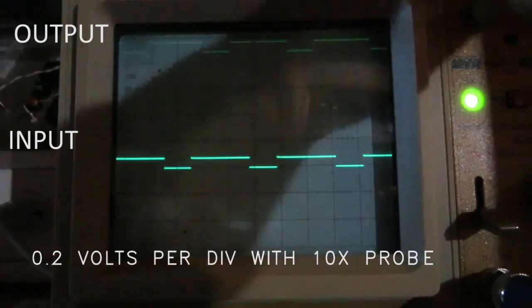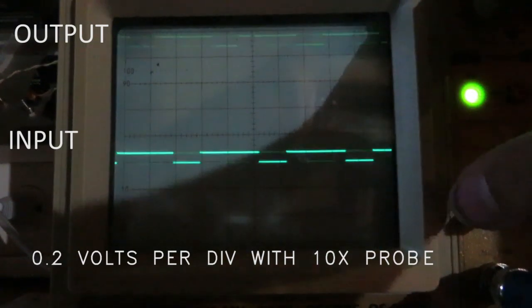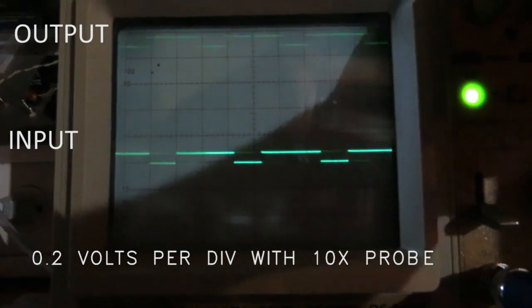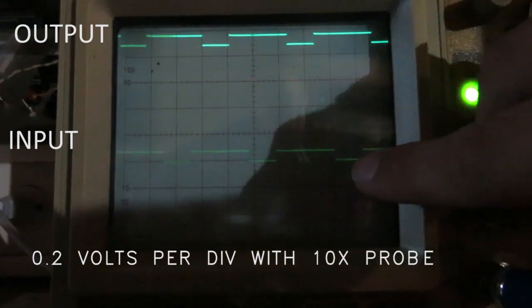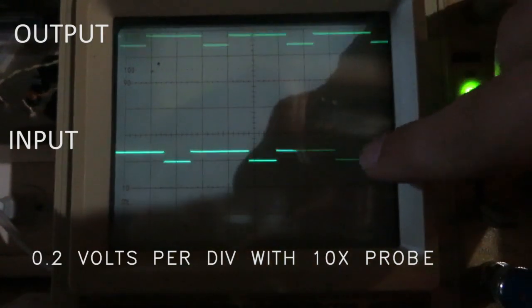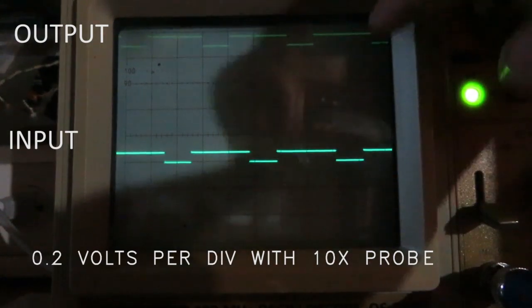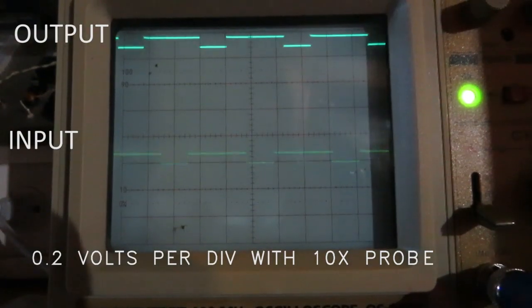So you can see it's using amplification, and you can also see here that this is a common emitter amplifier. We'll do a video on those later, but you can see that every time this side goes up, this side is going down. You can see that. And every time this side goes down, this side is going up. So this is a common emitter amplifier which inverts the incoming signal.